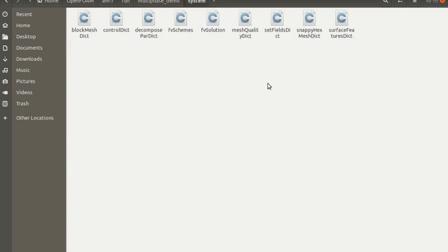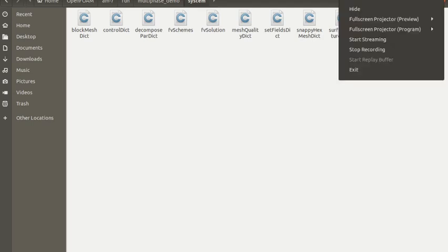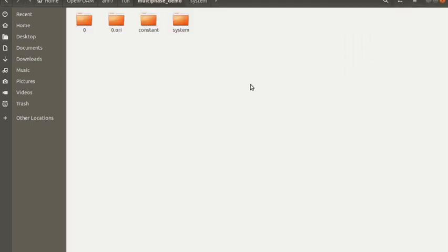Okay, next we can move on to the simulation procedures. The first command is to create the blockMesh around this geometry. Before running that command, we have to ensure that the data that we gave in the blockMesh dictionary is slightly greater than the bounding dimensions of the geometry.